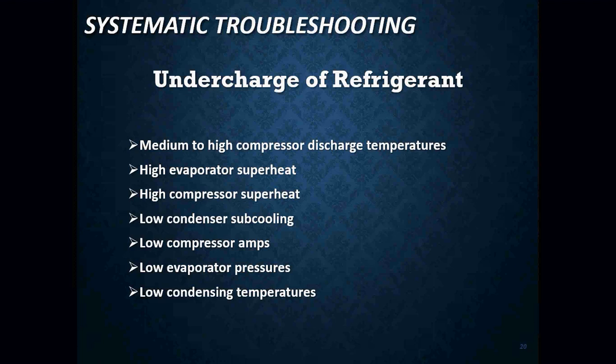Undercharge of refrigerant, you're going to see a couple different things. If it's undercharged, you're going to have medium to high compressor discharge temperatures, which means the discharge line is going to be extremely hot.